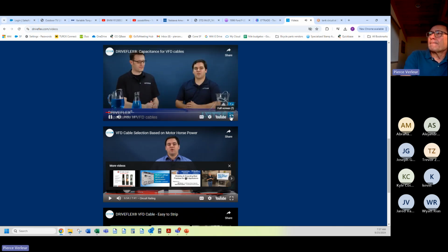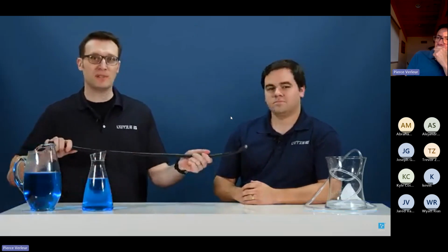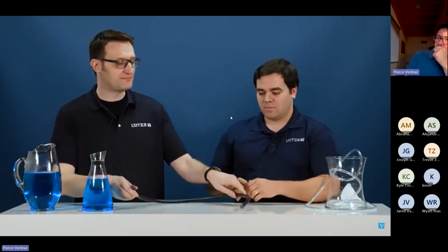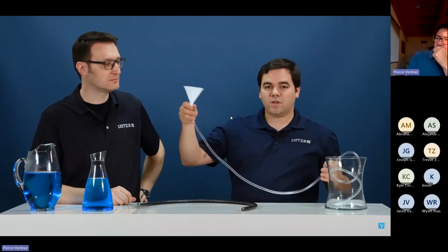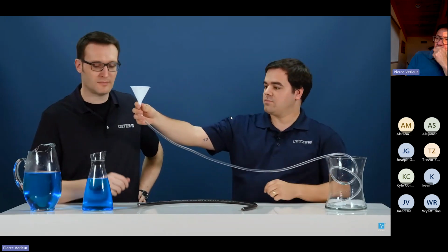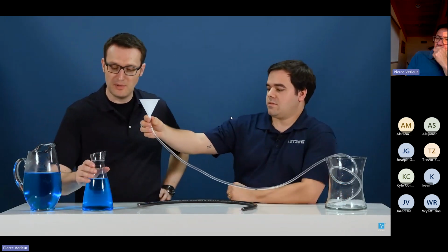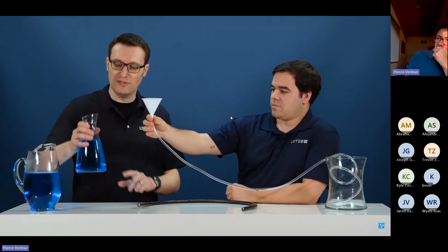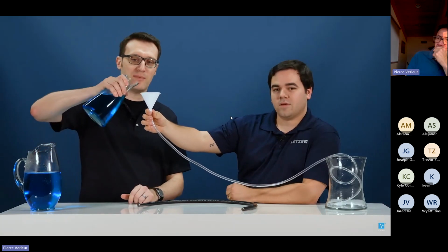Hi, I'm Stefan. And I'm Matt. And today we're here to talk about capacitance in VFD cable. We brought one of our DriveFlex VFD cables with XLP insulation. And when we talk about cable capacitance, what we mean is the ability of this cable to store an electric charge. So think of this cable like this tube here. So we have some props that will help you understand how capacitance works. This is the energy coming from your drive.